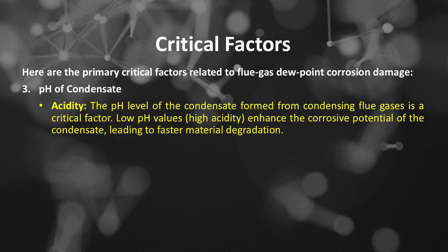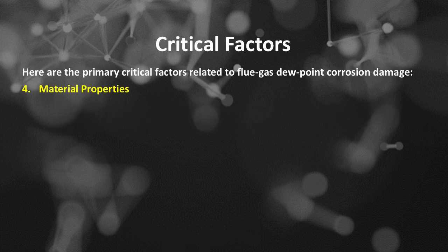Acidity, the pH level of the condensate formed from condensing flue gases, is a critical factor. Low pH values, high acidity, enhance the corrosive potential of the condensate, leading to faster material degradation. Number 4 is material properties.